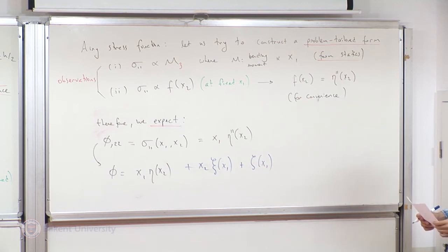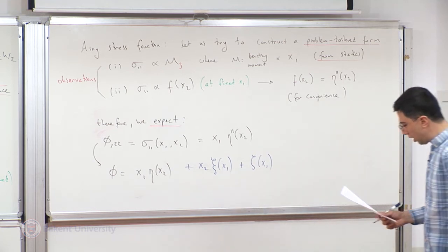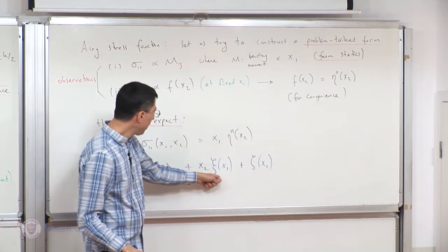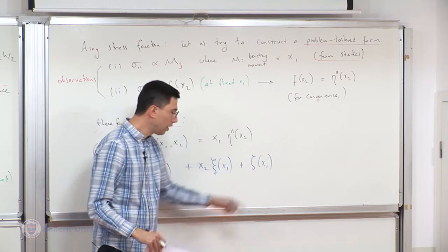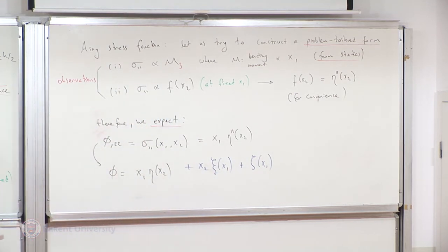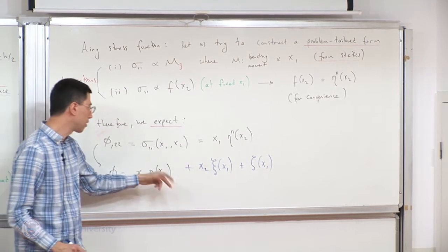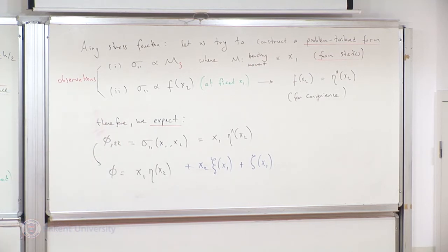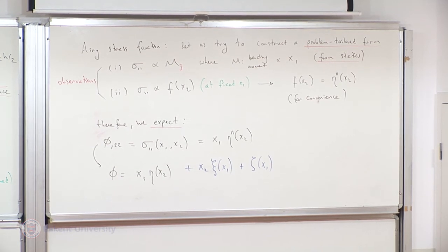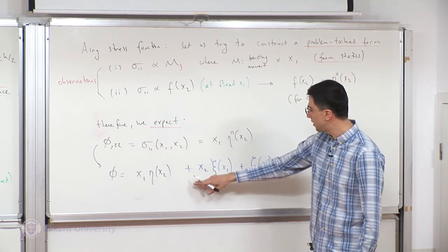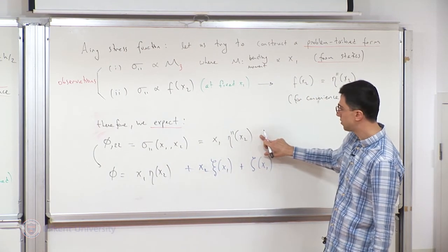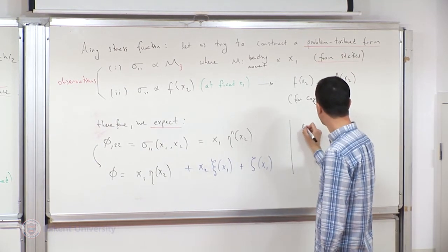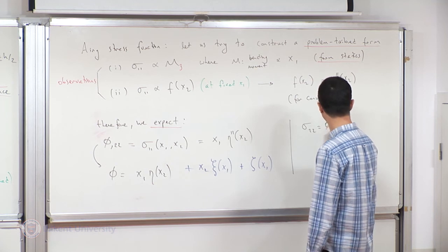So this is the general representation of the Airy stress function. Usually when I have a function that depends on only one coordinate, I really drop that representation. But in this case, I will have something that's a function of x2, another thing a function of x1, plus they're in Greek alphabet. So I'm going to try to explicitly indicate the dependence of the functions, whether they are on x1 or x2. Based on these, I can calculate not only sigma 1. If I take two derivatives with respect to 2, that's sigma 1. But I can calculate also sigma 2, which is phi, comma 1.